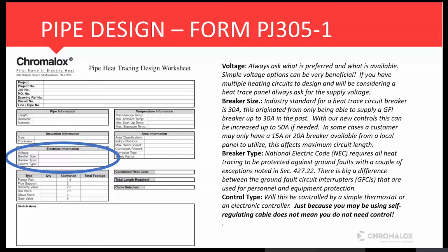Simple voltage options can make a huge difference in the overall design. If you're dealing with a panel, if we already know this is going to be installed in a panel, make sure you ask, what is the voltage, the feeder voltage coming in to that heat trace panel? What is the supply voltage? So kind of a twofold thing there on voltage.